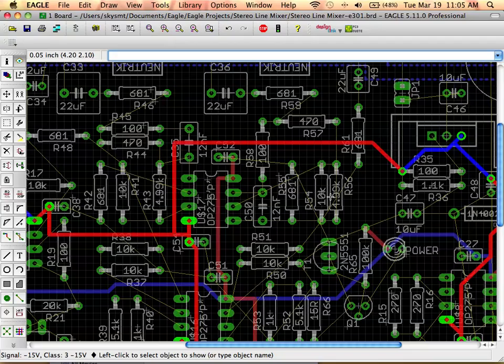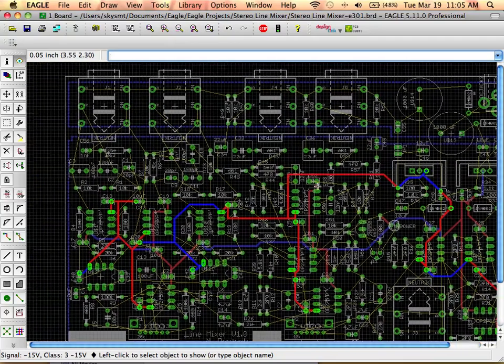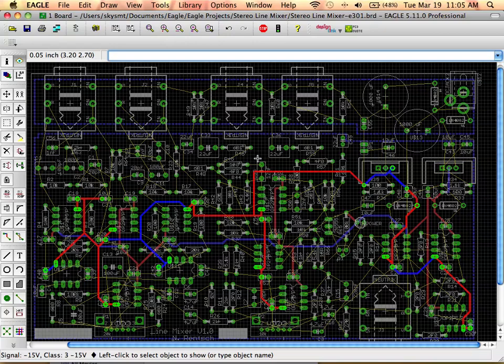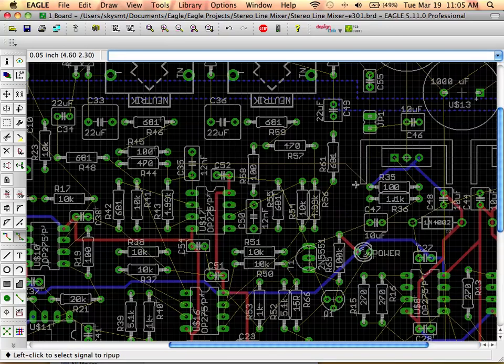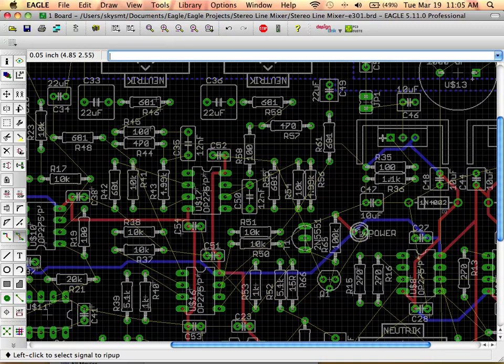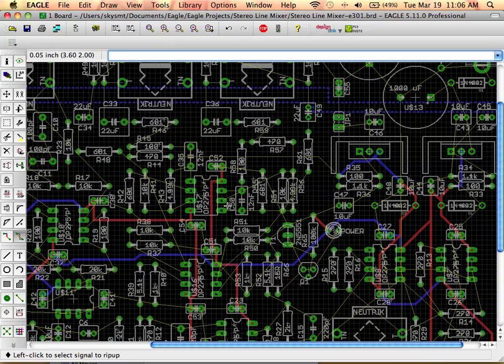I mean, I could change things at this point. If I didn't like this going up over here for some reason, I could change that. And you could rip up only this part of the path here and say, okay, well, I didn't like any of that, and now I want to route this. I'm just going to route it underneath. Why not just, well, this may want to minimize going underneath for interfering with the ground plane, but I'll do that. Why not?